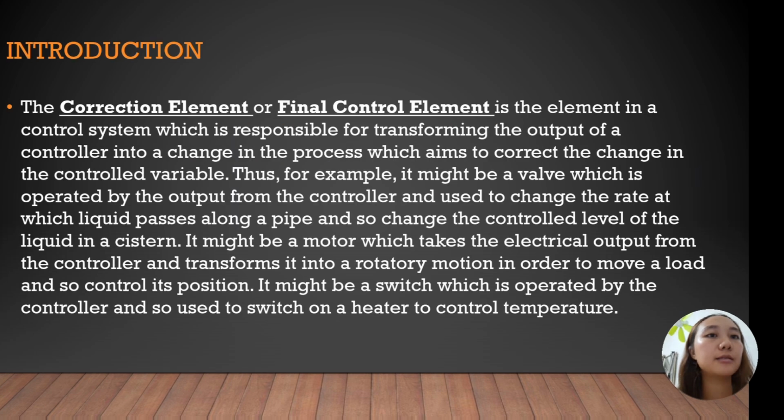Correction elements. The correction element, or final control element, is the element in a control system which is responsible for transforming the output of a controller into a change in the process, which aims to correct the change in the controlled variable. Thus, for example, it might be a valve which is operated by the output from the controller and used to change the rate at which liquid passes along a pipe and so change the controlled level of the